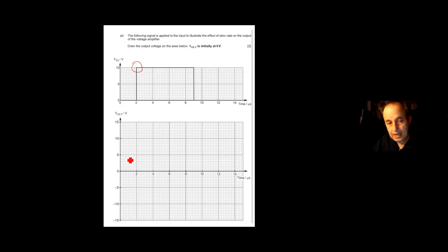So if it's ideal, it's an inverter as well. What it would try to do, if it's ideal, is drop straight away to -13, keep it, and then drop it. So this would be an ideal op amp, right? But op amps are not ideal because they have this thing called a slew rate. So they can't cope basically with giving you an instantaneous change like that.